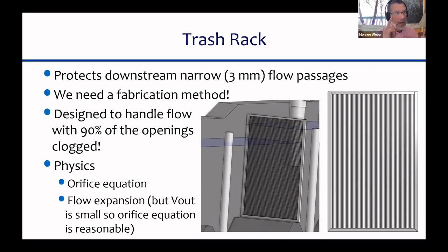If you have a pipe that's discharging water into a big lake, even if the flow out of that pipe is laminar, all of the kinetic energy is lost when it flows into the lake, and that is v squared. So it always scales with v squared when you're doing an expansion. Okay, man, you guys make me happy. You got v squared as your friend now.